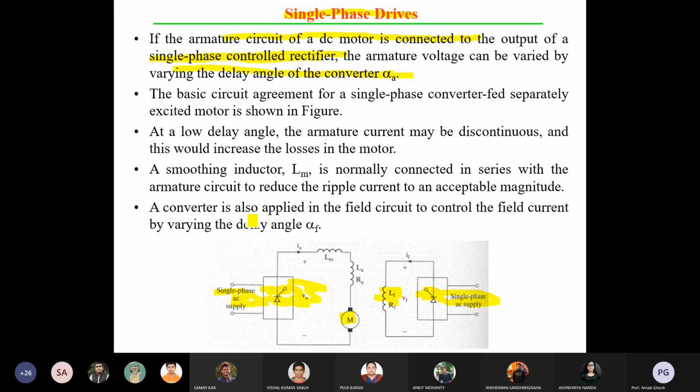There are three terminals: an inverting terminal, a non-inverting terminal, and the output terminal of the op-amp. You give a sinusoidal signal to one of the input terminals, and the other terminal you connect to ground. Now you are using unity feedback. What is your output? Definitely you will get a square wave.